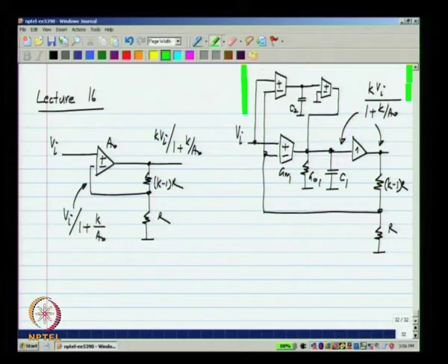Also, keep in mind that we said the circuit below already reaches steady state, and when it has reached steady state, the other controller appears into the picture. In reality, both are working simultaneously. What we really mean is that the second circuit, this integrator and the transconductor signal path, operates more slowly compared to this particular circuit. This is so that what this transconductor here should be measuring is the steady state error between these two, and it is providing a compensating current which is related to the integral of that steady state error.